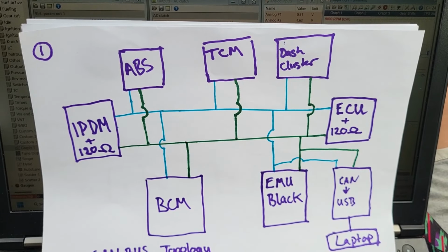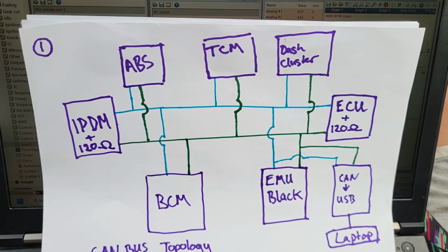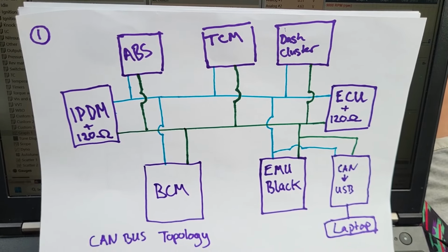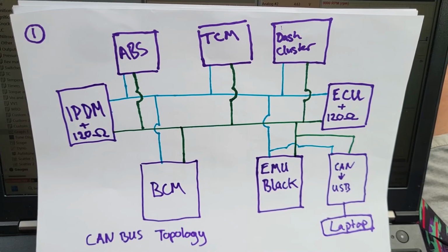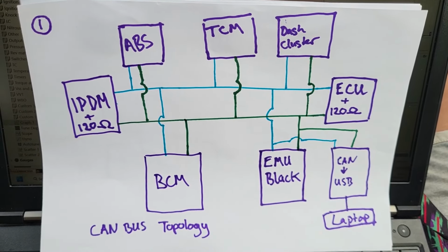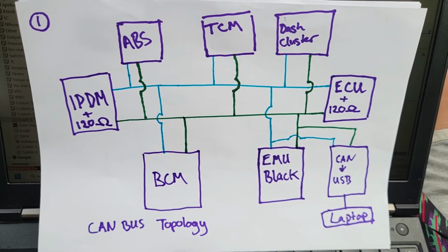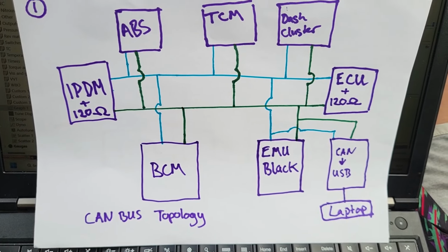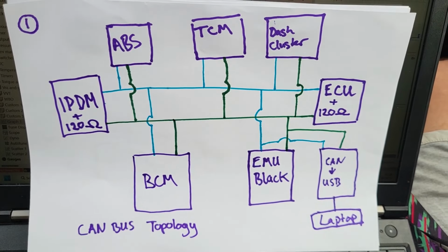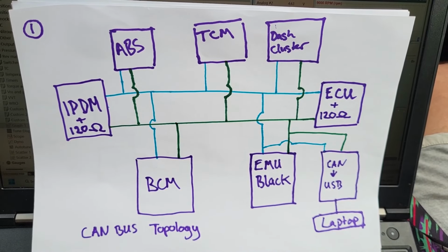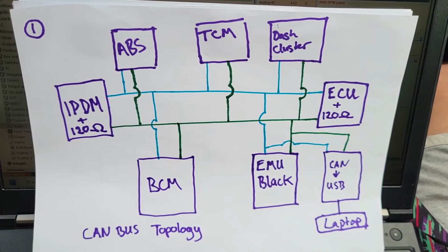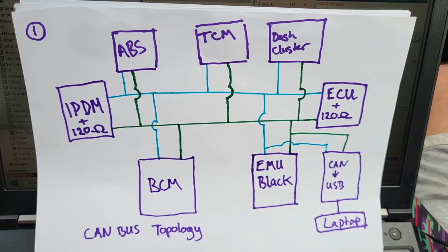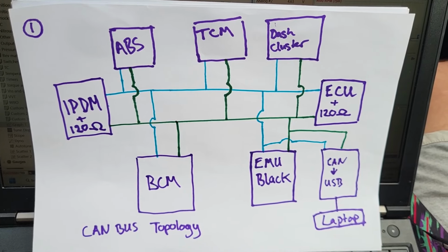It runs at 500 kilobits rather than a megabit, which some of the more aftermarket stuff would run at. So if you're running a pure ECU Master install and communicating between their devices, you'd probably use a megabit connection. Or if you're doing it with an AIM ecosystem, Haltech, whatever. But this being an older vehicle, turn of the millennium, it's using 500. So that's what this network runs at. And when we set up the CAN sniffing software in a minute, that's what we'll be setting it up as.